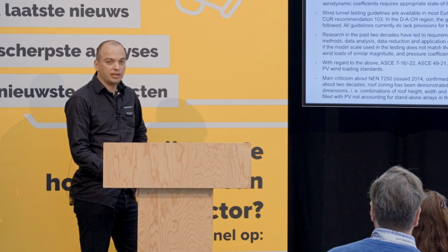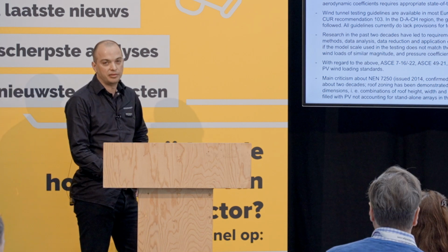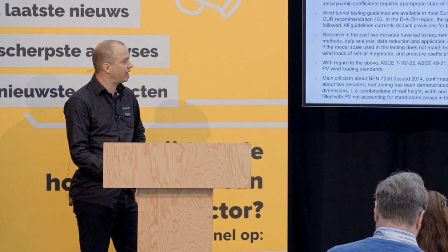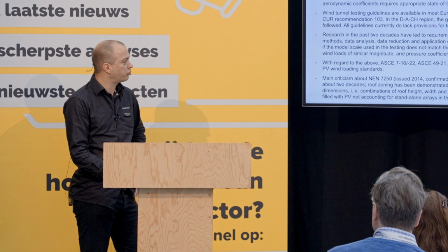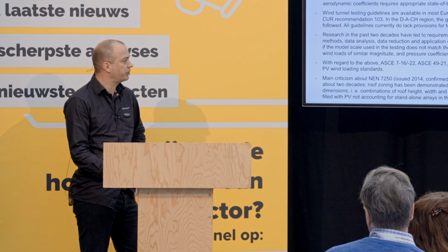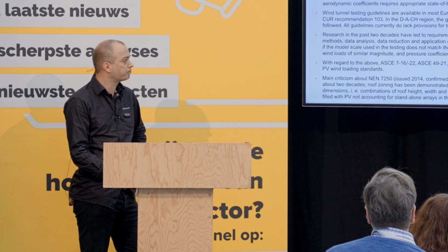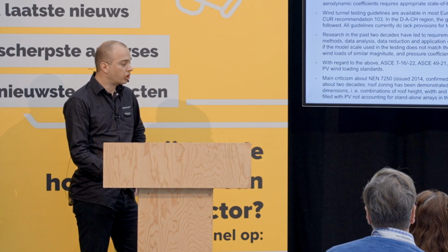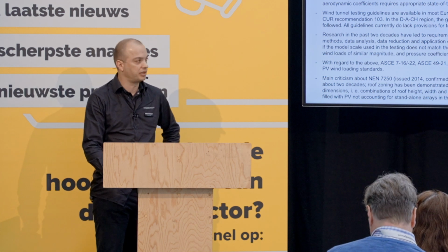Wind tunnel testing related to building structures needs to be conducted in boundary layer type wind tunnels, where the spatial and temporal correlation of fluctuating pressures measured using high frequency sampling is covered. Moreover, the analysis of aerodynamic coefficients requires appropriate state-of-the-art methods.